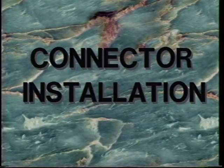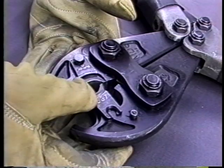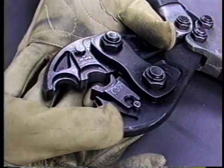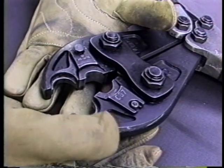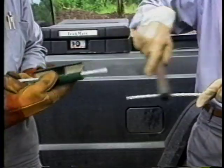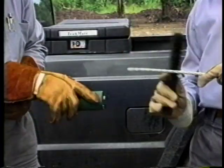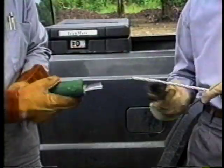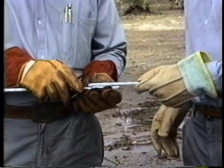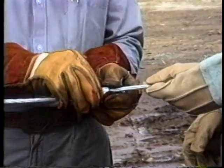Connector installation. Once the appropriate connector and dies have been identified, the compression tool is checked for calibration and removable dies installed if required. Prepare the conductor by wire brushing. Then, place the conductors to be joined into the grooves of the connector and close the metal tabs.